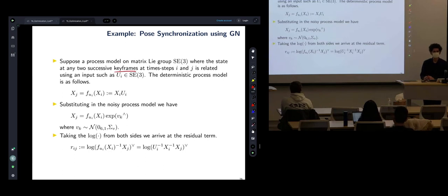You can set a threshold on the magnitude of twist, the delta pose you move, regardless of time. You can set a threshold on the number of features that you lose when you track. Probably you don't want to rely on one, maybe a list of 4, 5, 6 conditions.